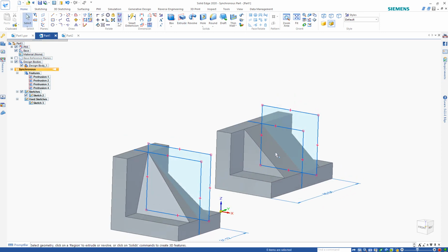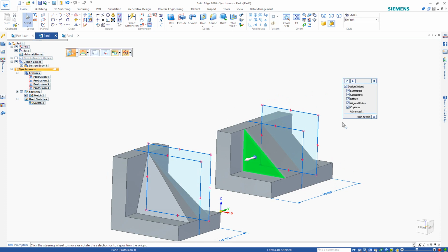It's almost done. The last thing, we're going to use the wheel to turn it. If you click on the surface, you'll realize that it's only one direction arrow. You might say, where is my wheel? It's easy to bring it up, you just click again on the center, and it will pop up. Since we want to turn along this bottom axle, we just snap the wheel to the bottom, and click on the wheel.